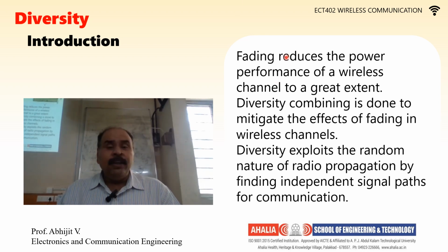First point is that fading reduces the power performance of the wireless channel to a great extent. That means that fading reduces the signal to noise ratio at the receiver end. In diversity, we send the same signal through multiple paths, and these independent paths are combined in such a way that fading of the resultant signal is reduced.